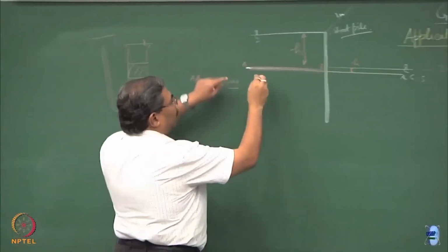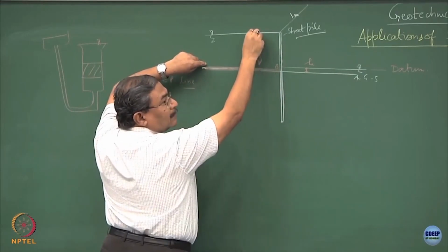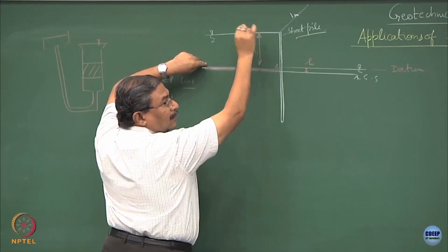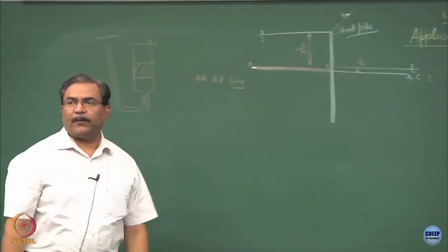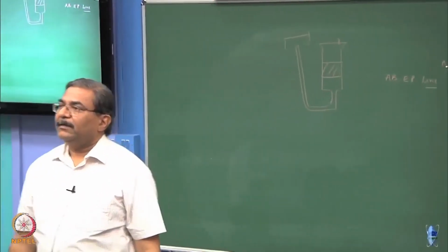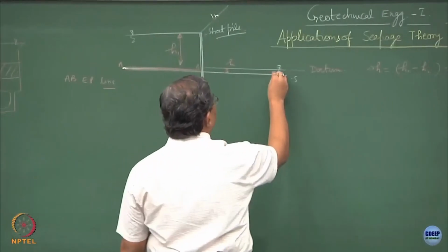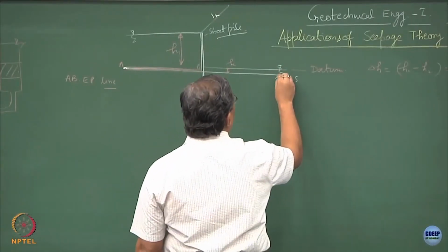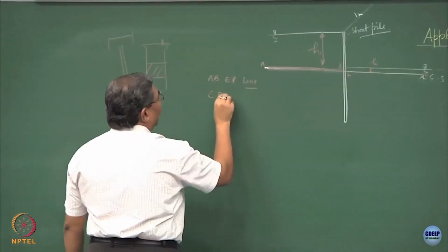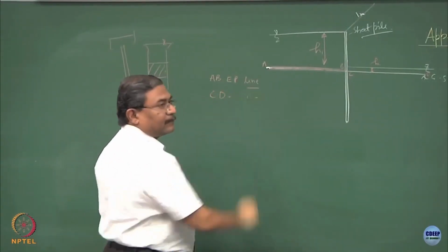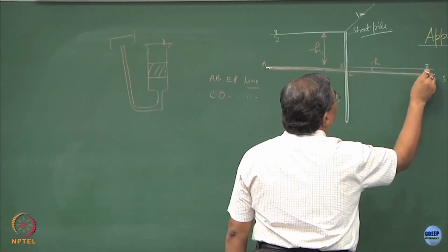Is this point clear? Put a piezometer at any of these points, the height of the water column is this, clear, the piezometric head. So, this becomes one equipotential. Where is the another equipotential in this figure? Sorry, you are right, CD. So, this is D and this is C. So, CD also happens to be an equipotential line. Have you understood this? What abnormality are you seeing?